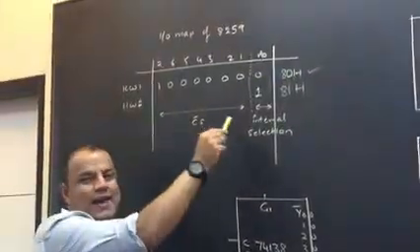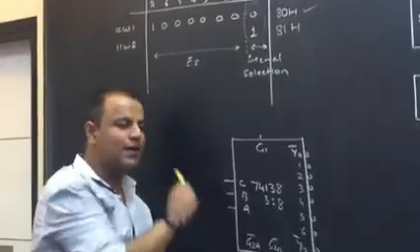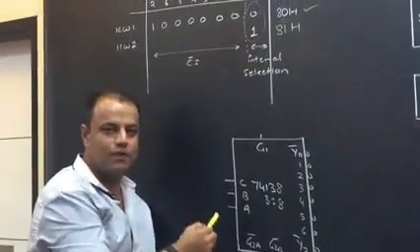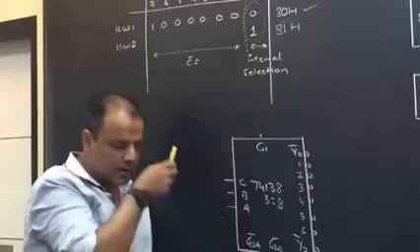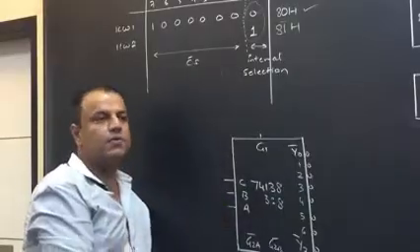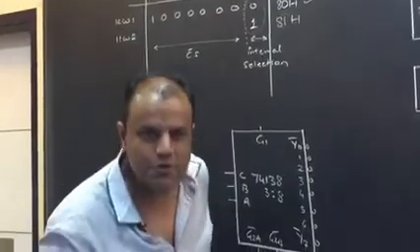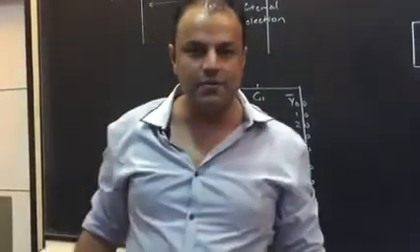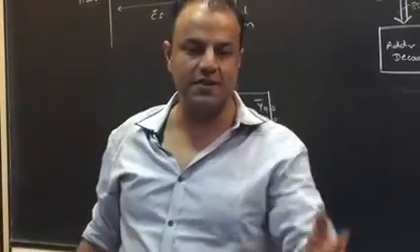Now, you can give any 3 lines to the decoder. I repeat, any 3 lines. You can give A7, A6, A5 or A4, A3, A2 or A2, A1, A3, in any order. It doesn't matter. Now what do you want to do? You want to make a random solution or a standard solution? Standard solution, textbook solution, easy on the eye. Examiners know what the solution is supposed to be. They see the correct solution.